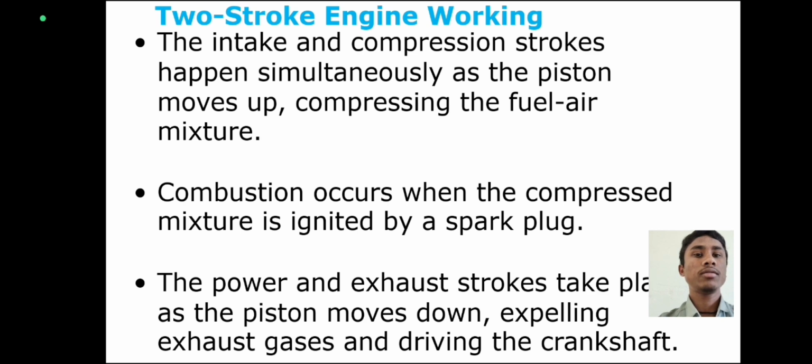Two-stroke engine working: the intake and compression strokes happen simultaneously, and the piston moves up, compressing the fuel-air mixture. Combustion occurs when the compressed mixture is ignited by the spark plug. The power and exhaust strokes take place as the piston moves down, expelling exhaust gases and driving the crankshaft.